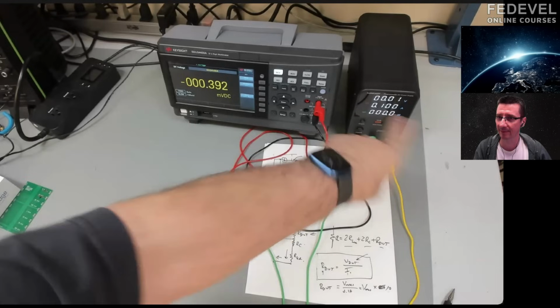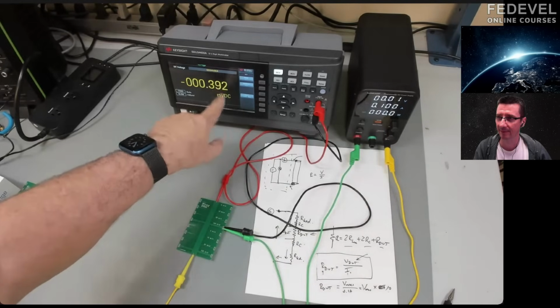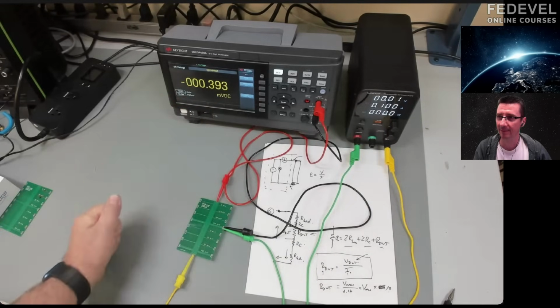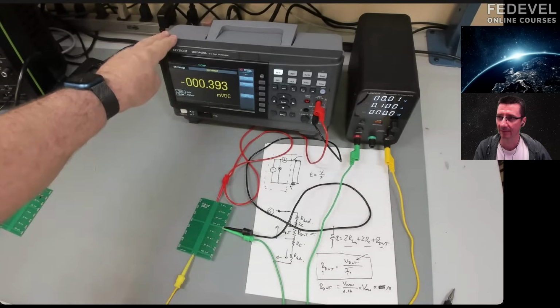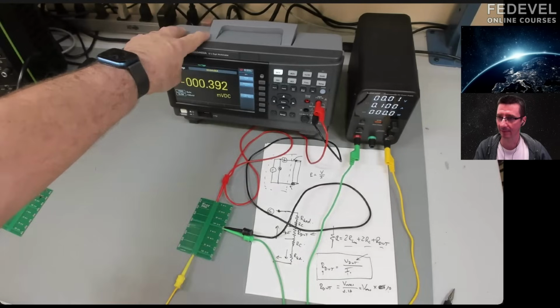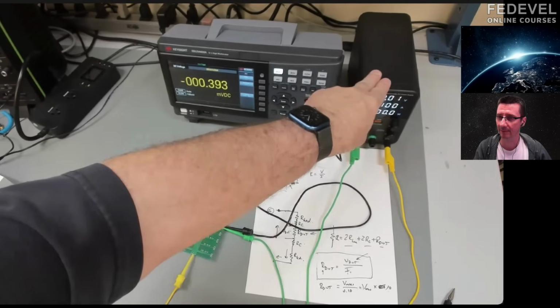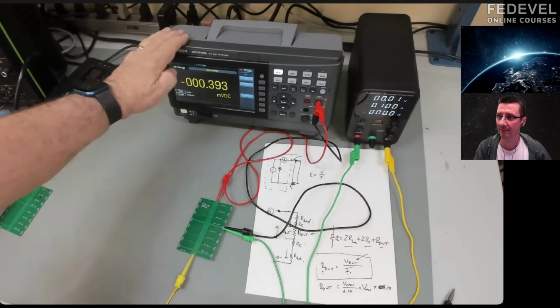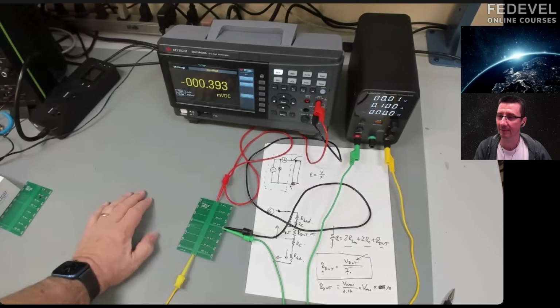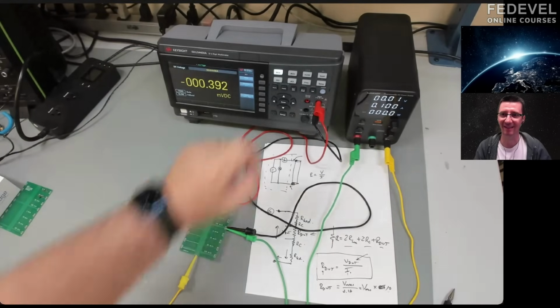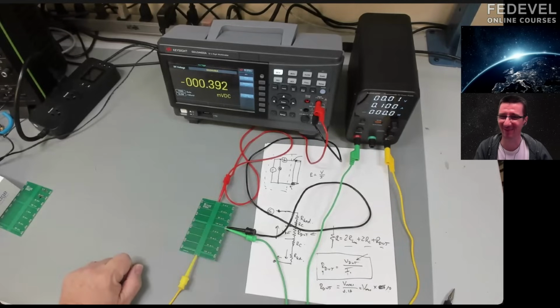So even with 100 milliamps, we get a much finer resolution with this method than we could with this guy all by himself. And you could literally use almost any digital multimeter and any power supply to do this measurement. You don't need a really fancy high-end multimeter to do it. But you need a special power supply.